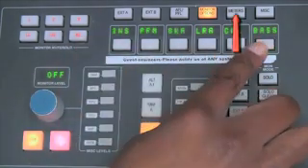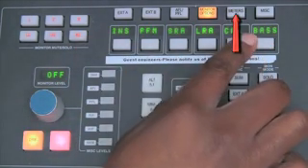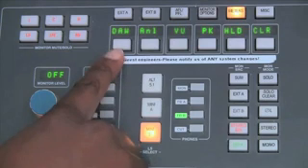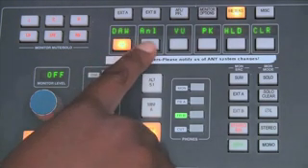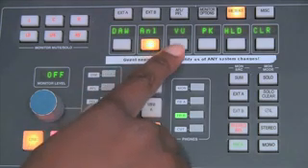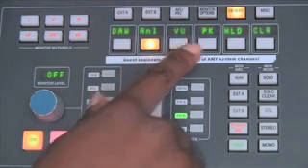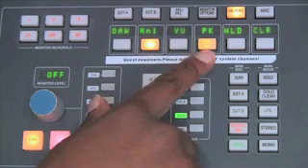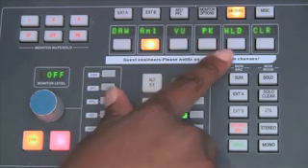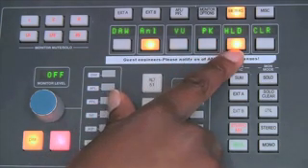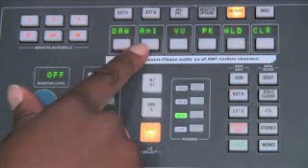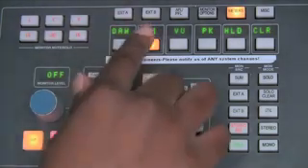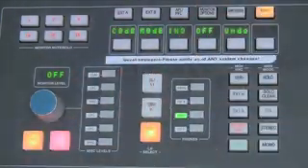The meters option allows you to choose how you want your channel meters and your center section meters to react. You can have them show your DAW meters, your analog section meters, or choose what your VUs show in your center section. So whether you want it to show the peak meters and whether you want the peaks to hold. And if you do have the peak hold on, you can also clear the peaks. Activating peak hold holds the peak infinitely, and you just get rid of this by hitting clear.